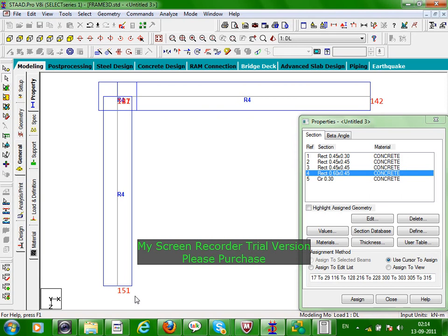Now observe carefully: this rectangle is the column, and this is your beam. The column is of size 600, and this is R4, okay, I am looking, not randomly telling, the beam is of 450 size. So what will be the projection beyond this line, and what distance do I give so that this column becomes flush at this level?